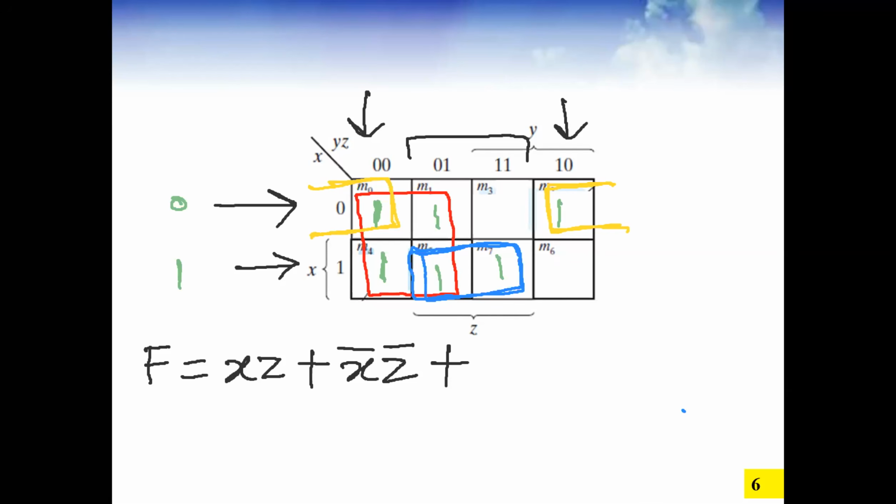These two. Because this is covering the red one. So if you look here, this 0 bit, that is y and z. So z is changing. For the first column, it is 0. For the second column, it is 1. But y is 0 for both the columns, first and second column. That is, for the red, we are focusing on the red group. So what is common? Y complement. Correct or not? Y complement. Yes. Clear? Okay. So this is our answer. This is the way.